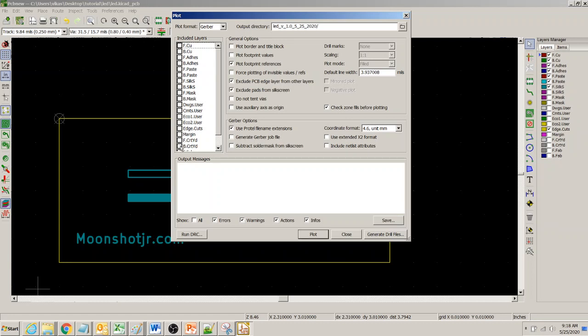The files that I need to generate in the Gerber are F.Cu, which is the top layer copper, and the bottom layer copper. This is just for a 2-layer board for simplicity, but the similar thing could be extended to 4 layers and more layers. We certainly want the top and the bottom silkscreen layer. We want a board cutout layer, which is Edge.Cuts, which shows the board cutout and any internal cutout. So these are the minimum number of files that you need, but of course, also the top and the bottom